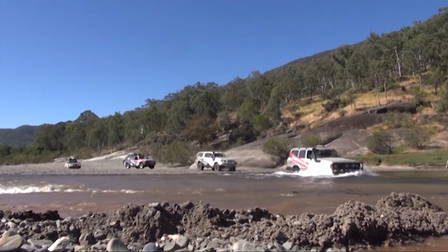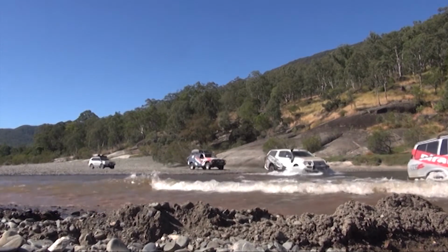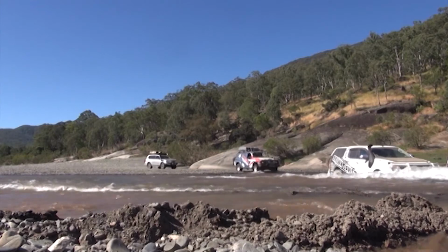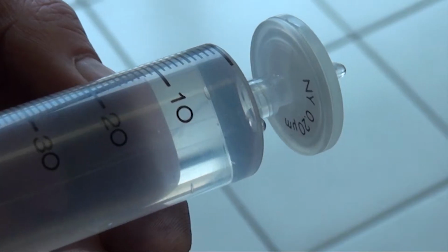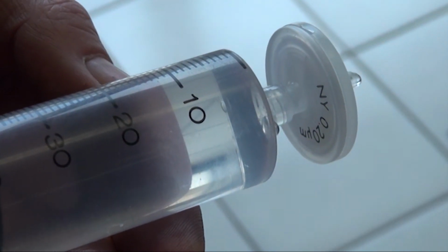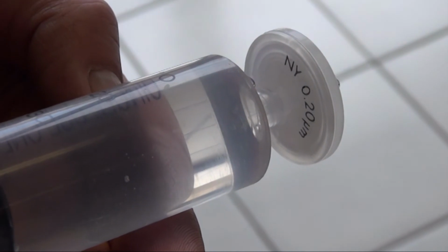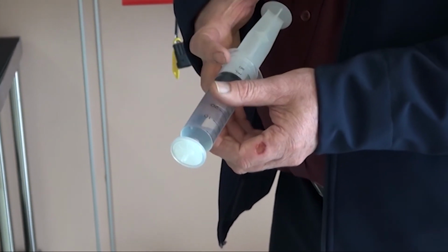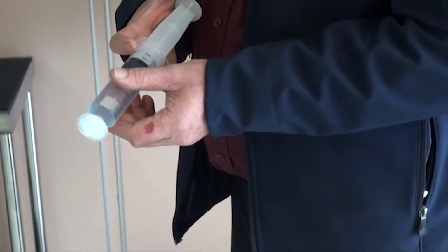The other misconception is that a filter will stop water. Predominantly, a filter is not designed to stop water. It's designed to control particulates. And for the purpose of that exercise, we've got here a 0.2 of a micron filter. 0.2 gives us basically 1/10 the size of the factory filter. And we'll demonstrate that water can easily pass through that filter with very little effort. So as you can see, that a filter in a motor vehicle will definitely pass water.